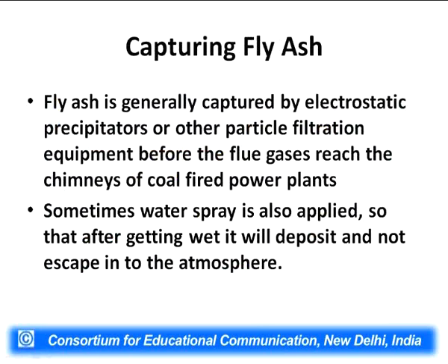Now, I must give some information about the capturing or collection of fly ash from the flue gas. Fly ash is generally captured, as far as its removal from the gas stream is concerned, with the help of ESPs, or electrostatic precipitators, or other particle filtration equipment before the flue gas reaches the chimney, because once it reaches the chimney, it can't be separated out.